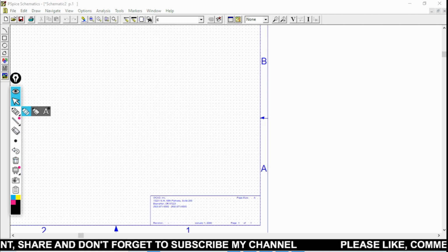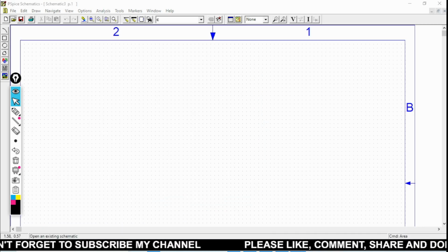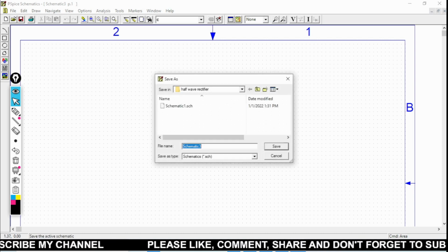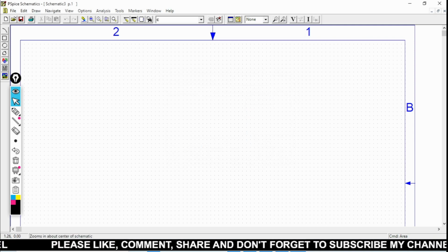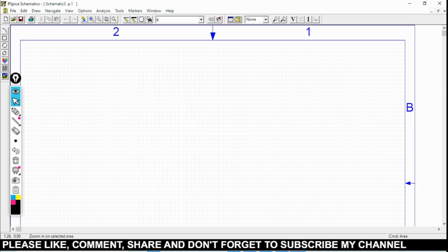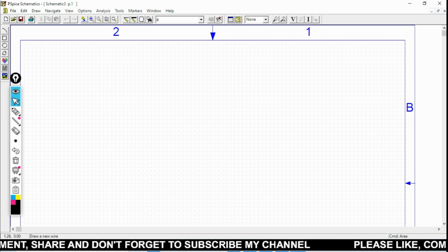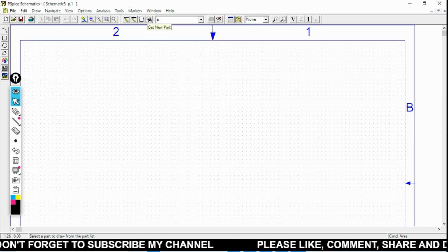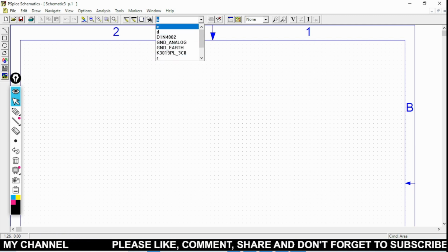This is something available here called the toolbar. You can see here, we can take a new page. If we want to open some previous project, we can open it from here, and we can save here. Then we have shortcut keys here: zoom in, zoom out, and so on. Fit to page. Here is the wire option, where you can draw a wire. Here is an option called draw bus. Here is draw block. Control G is get new part. You can take it from here. The library shows which components I have taken.